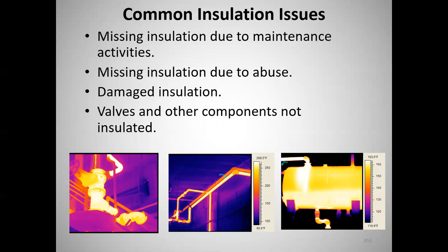And then this tank, this was what functioned as their deaerator tank. It's not really a deaerator tank. They're just dumping their condensate back in there. And you can see it wasn't insulated, not a stitch anywhere. You can see the water level in the tank with the infrared camera. That white part on the bottom is the hot water, and above that, it's just hot air. And you see the little vent on it. It's cold, so it's not flashing. If it was hot enough, you'd have flash steam, and that little vent would be hot, but it wasn't.